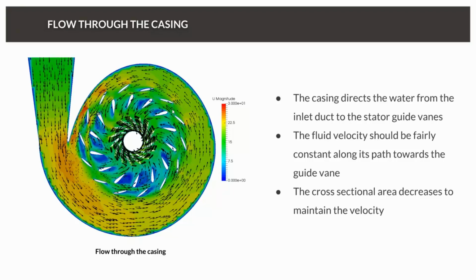What we can see with this design, and it's not great, is, especially take a look at the stator at the bottom down here, we can see large regions of blue basically. So the flow is coming in here and it's basically going around in between the two groups of stator blades, and it's not passing into the middle and getting into the turbine, which is where we need it because that's where we can extract the energy. So already, we could think, okay, there are some changes we can make there.